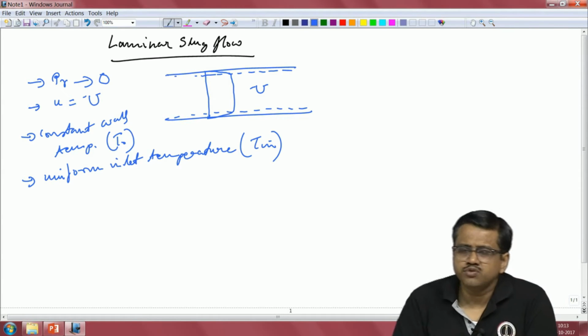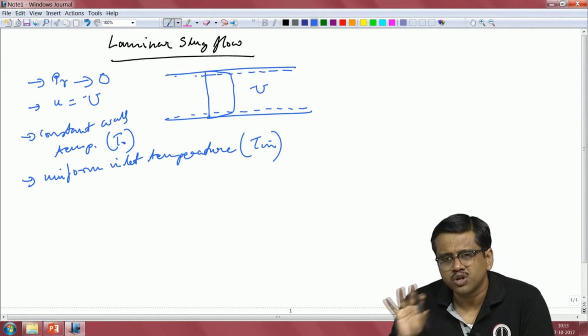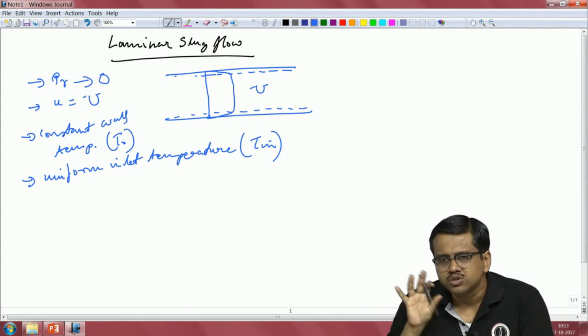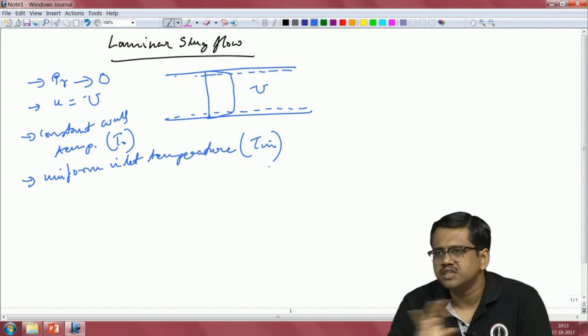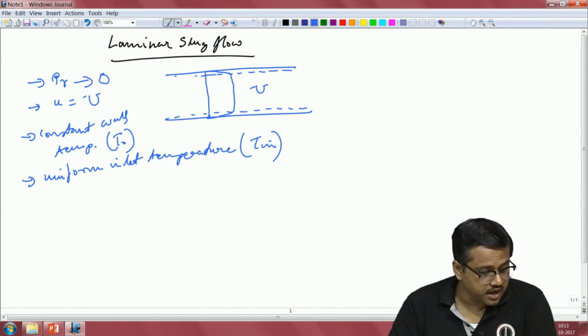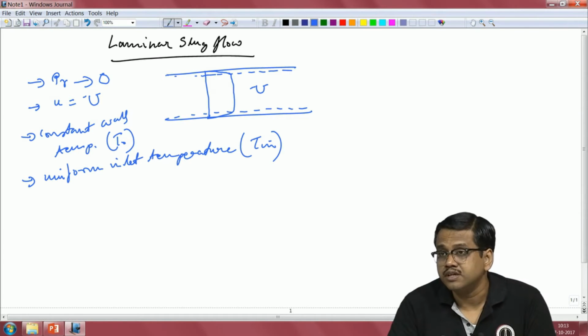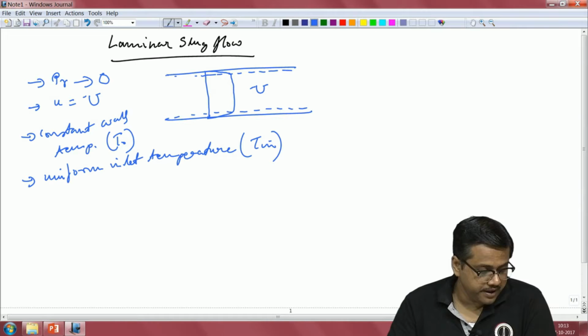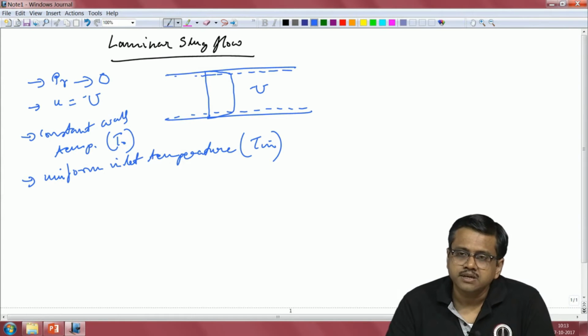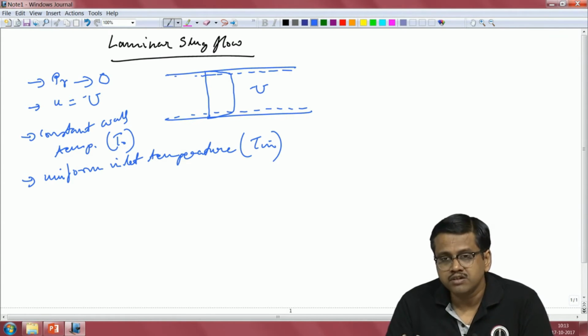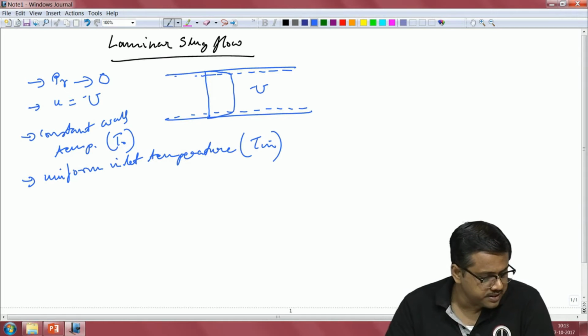So this happens a lot in the food industry, because if you are trying to push, say, solid food or semi-liquid kind of food through the pipes, there usually the boundary layers are very thin. As a result of that, your velocity is kind of uniform across the cross section. That means the r dependence is not there anymore. That's what I am trying to say. But if the pipe is very long, ultimately this velocity profile will develop. The thinness assumption is going to be no longer valid, but for all practical purposes, for the current situation, this pipe length is short enough. It's still long, but short enough relatively, so that the velocity remains the same.